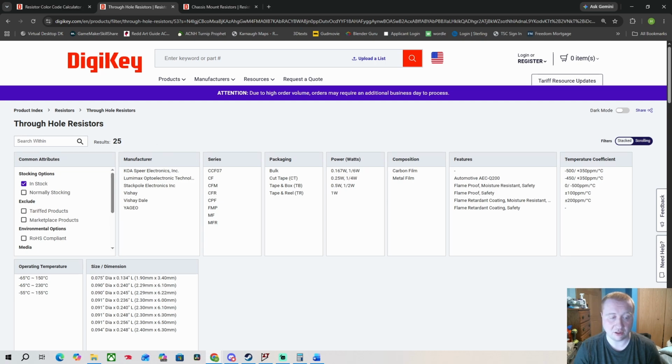So back to the explanation here. The maximum voltage that I could probably safely use is the square root of 1 times 10,000, which is 100 volts. There might be more information in the datasheet that describes something called a limiting element voltage too, which may be lower than the calculated voltage that I just gave. Always go with the lower value.